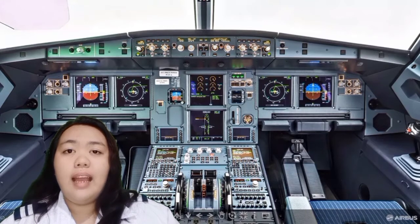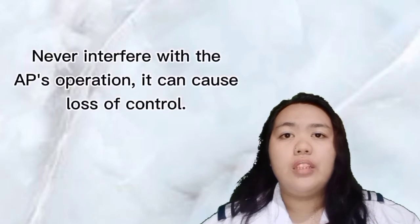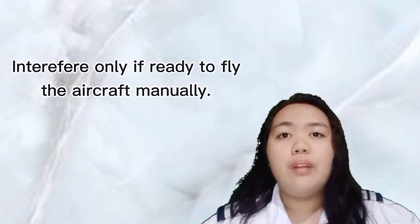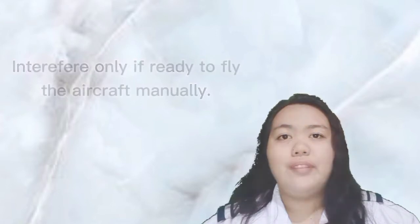Now, all the pilot has to do is to monitor the operation of the system and take proper action if any error occurs. On another note, if the autopilot is engaged, never try to help or assist it because interference in the operation may result in total loss of control. Only interfere if you are ready to manually fly the aircraft.